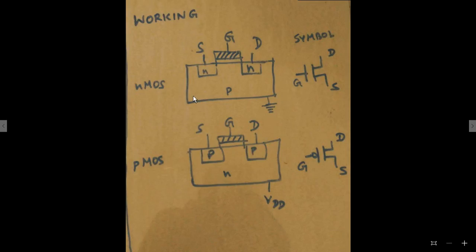So before going into this, I want to say one more thing. In case of N MOSFET, this body terminal is grounded just to make sure that the source and drain junctions are reverse biased. So the first thing is there are four terminals in N MOSFET, and the body terminal is grounded for the reverse bias condition to be ensured in source and drain of N MOSFET.